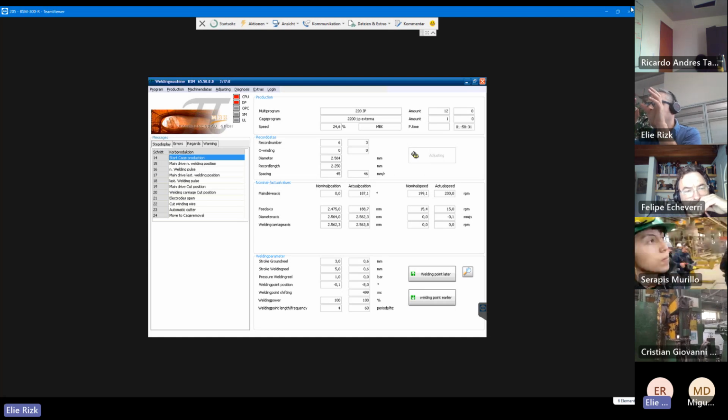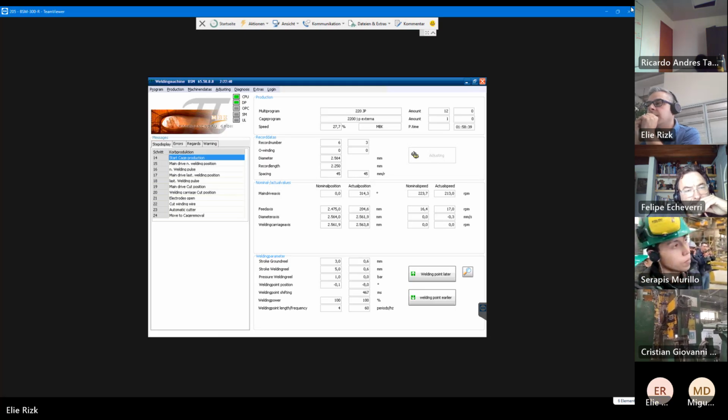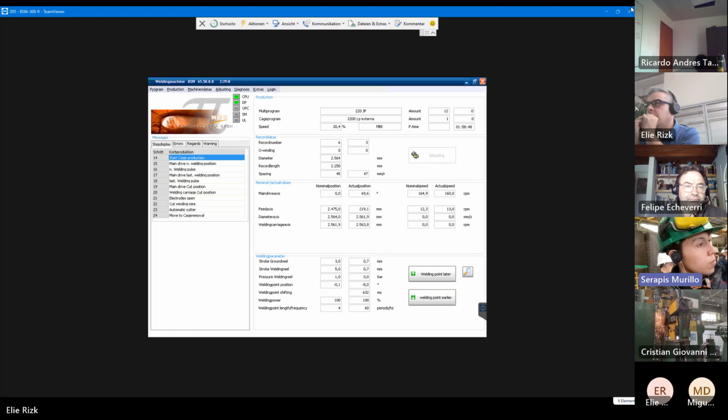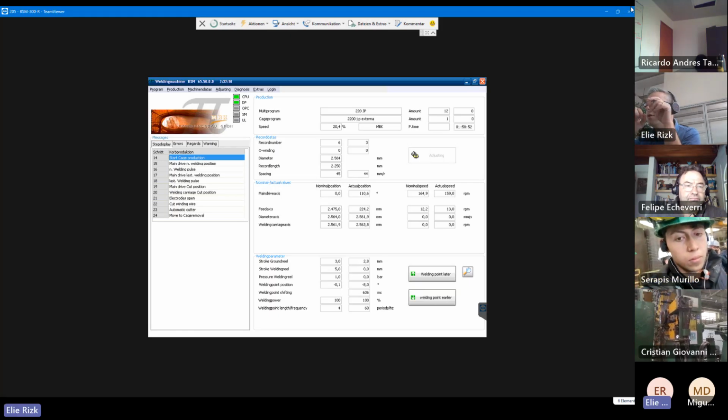But then you are sure that all the clamps are closing. Maybe you have a problem with some air. All of them, yes, they are closing, but they don't grab well sometimes. And you have enough pressure on the clamping bars, right?